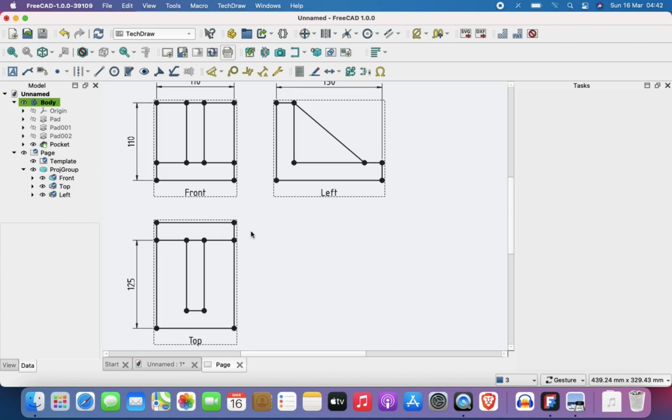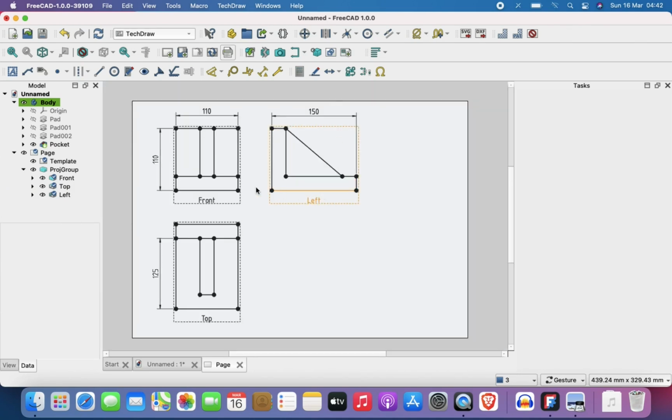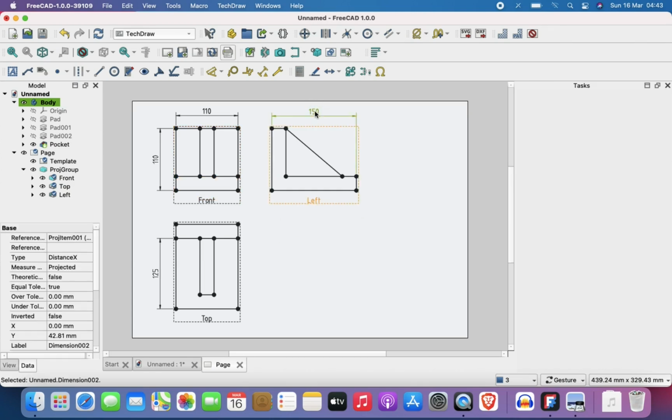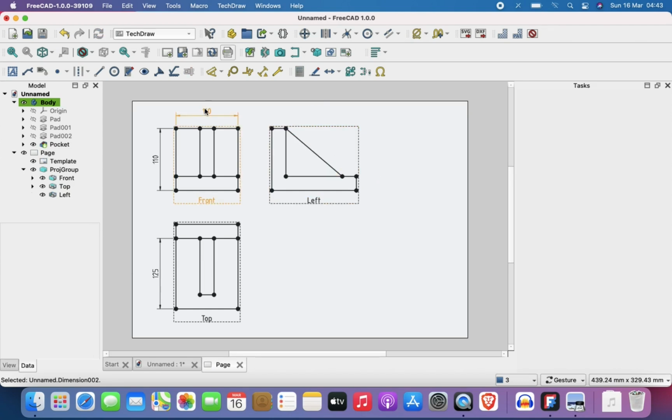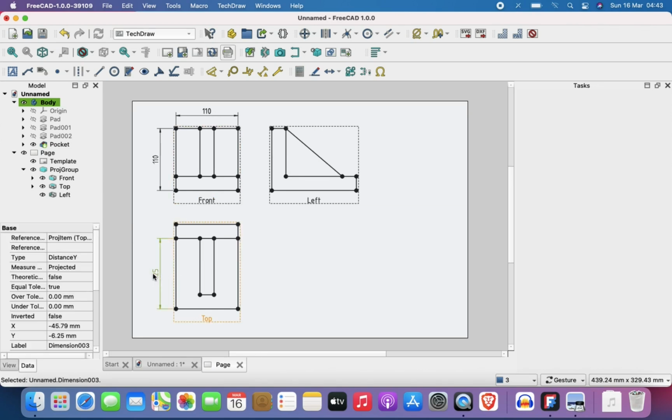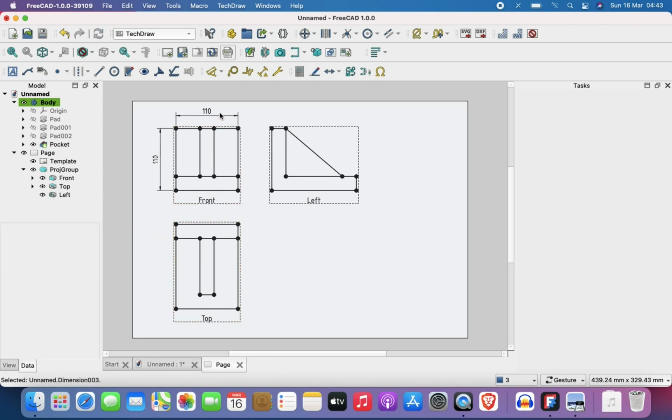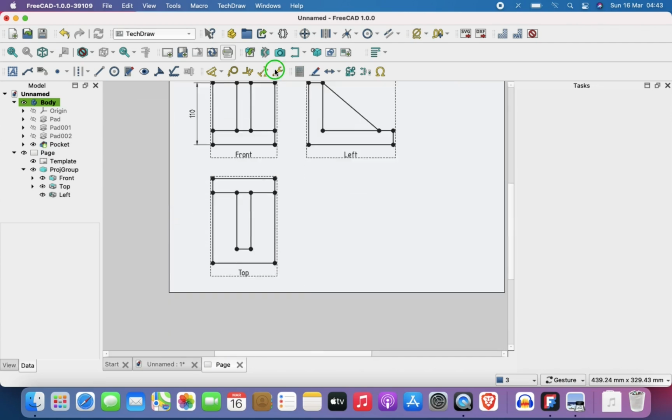Okay, so now I've shown you how you can easily put dimensions on this object, but I want to explain something about putting in redundant dimensions, especially if you are just starting out with technical drawings, generally as an engineering student or as an engineer, or as somebody that wants to get your drawings across to somebody that will manufacture it. So even though these dimensions don't have tolerances, it is important that you don't put in redundant dimensions, and let me explain what I mean by that.